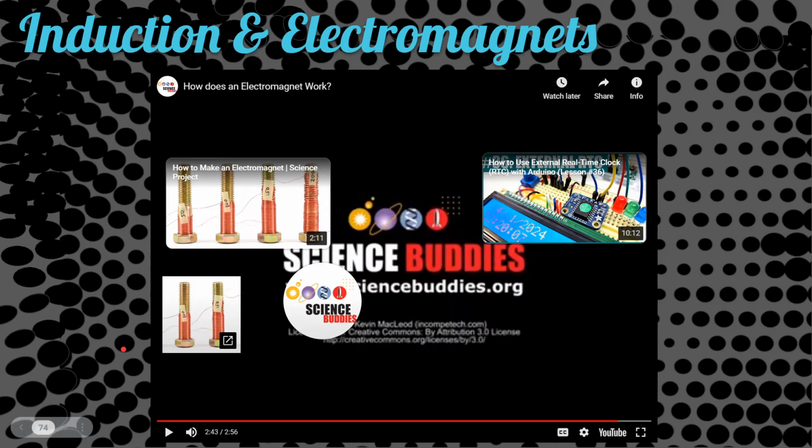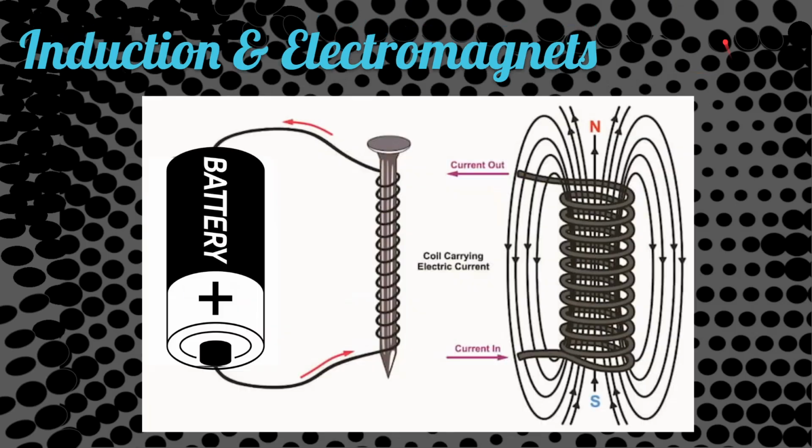Yeah, so if you do try to build one at home, you definitely don't put a paper core in the middle of it because he is right. It will get pretty hot, especially if you're using a larger battery, and that could cause the paper to catch on fire. So iron core is great though. So put a bolt in there or a nail in there. If you have another ferromagnetic material, those work too, but iron's going to work the best. Okay, so you could use nickel or cobalt, but iron's going to give you the strongest electromagnet.